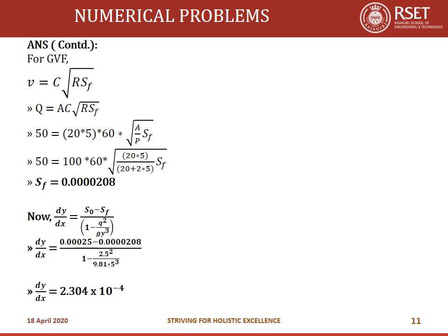This is how you solve problems in gradually varied flow using the dynamic equation. It's a very simple equation. I've just given you 3 variations for it because you can use either form. All of them lead to the same thing, which is S0 minus SF divided by 1 minus FR squared. But if you have these formulae ready-made in your hand, you would be easily able to apply it according to the data that is given to you.